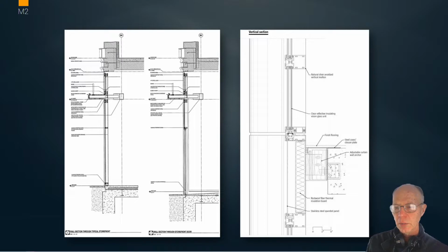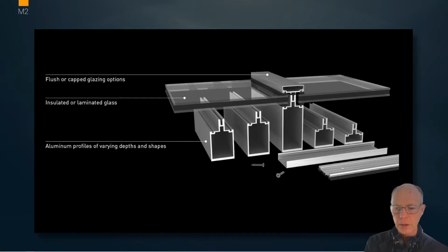Now we've looked at those extrusions, so when you see these, you can understand that those are the metal extrusions. We cut it in section. We can see that metal extrusion. We can see the two pieces of glass being held here. This is a spandrel area because it is at a floor system. So there's a clip coming out to attach the curtain wall to. So it's not unlike what we're going to be making in our drawing, and we'll actually do a little bit of this similar detail.